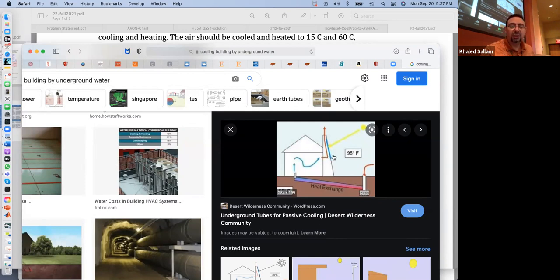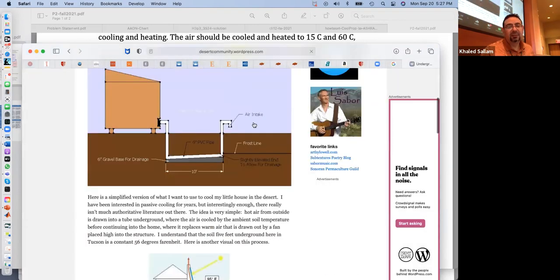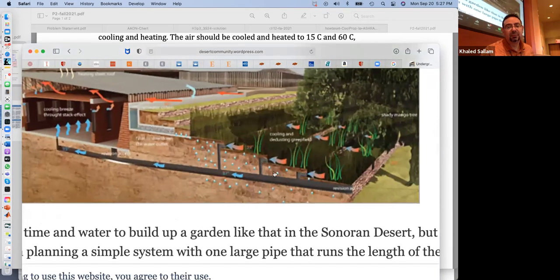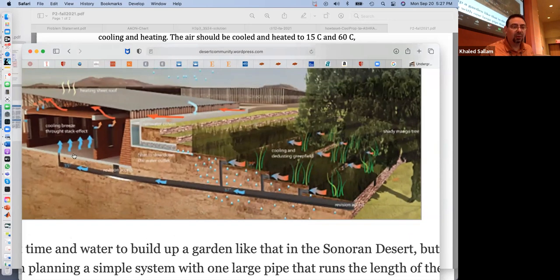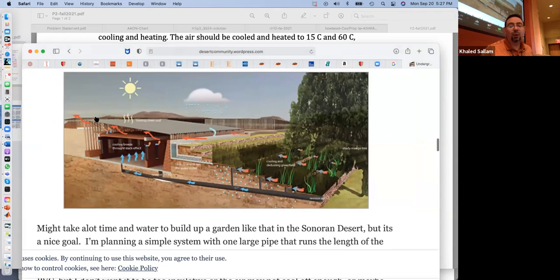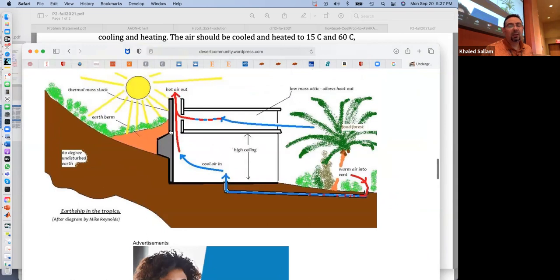And then you see this part too. This is where the sun is heating the chimney. Okay, so that's like passive cooling, underground for passive cooling. So the air is getting all the moisture from the ground, and it's helping it to cool, right? And the sun is driving the flow up the chimney. So the whole place is being cooled without any mechanical work.